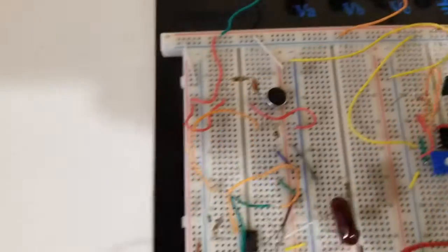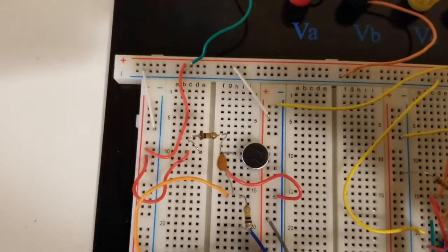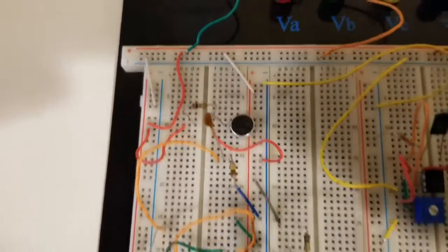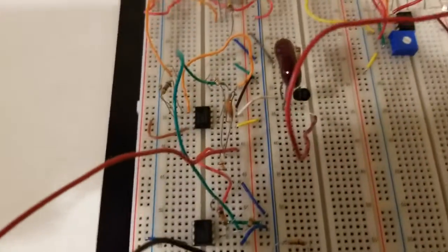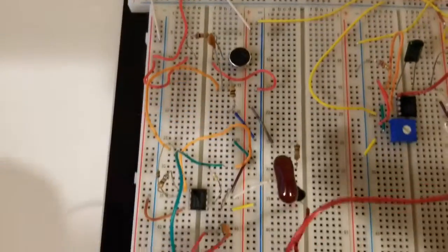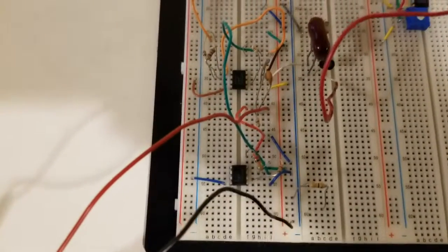So now going to the transmitting circuit, up here we have the microphone with the high pass filter with that capacitor and that resistor beneath it. Then over here we have the aux input, which is now connected into my laptop, going through another op amp. For the microphone, I use the op amp that's on the left side of this op amp over here to amplify it. And then for this one here, I just used a different op amp.